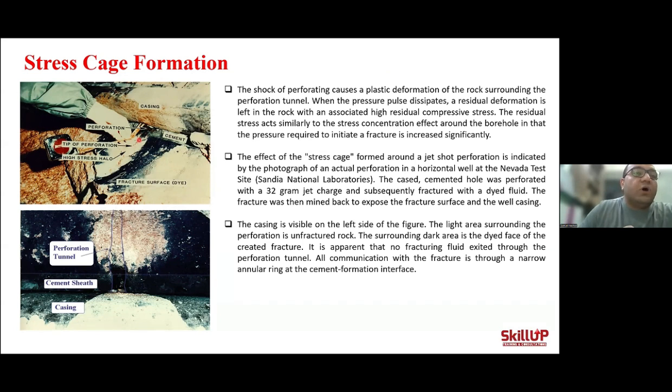And that's why frac fluid cannot penetrate this area, cannot go through the perforation tunnel, because this deformation is actually creating a huge stress, near wellbore stress. So the frac fluid will go through the least resistance. It will go through the cement and the formation, and it will avoid the perforation. This is very important to understand.